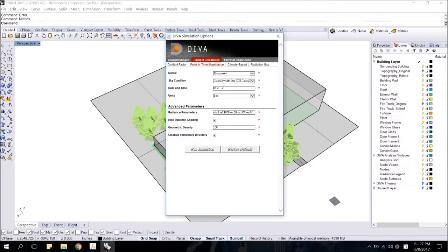I'm going to mention that I recommend playing with the illuminance analysis with 3 different scenarios. The first one is going to be June 21 at noon with the clear sky, which is the condition the building receives the largest amount of sunlight.